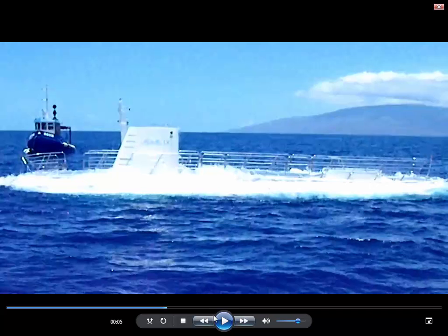There are pumps inside of the submarine, and there are these tanks at different places in the submarine where they keep a certain amount of water. You can just think of it as like a little mini swimming pool, although probably nobody's in there swimming laps. It's just these enclosed tanks, and when they want to sink, they'll fill the tanks up with water, and so all of a sudden now the weight is larger than the buoyant force, and it's going to start sinking downward. And then when they want to surface, they'll pump the water out, and then the submarine weighs less and it begins to rise.